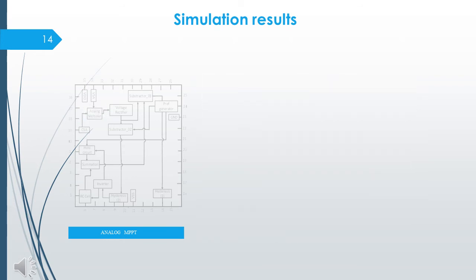The schematic circuit and its symbol of the Schmitt trigger, hysteresis, is shown in this figure. The following figure shows the transfer function of the hysteresis 1 and hysteresis 2 blocks. The bandwidth 1 of the hysteresis 1 block, well defined by epsilon 1 and epsilon 2, is set by the user and is based on current ripple and modulation frequency considerations. The bandwidth 2 of the hysteresis 2 block, well defined by epsilon 3 and epsilon 4, must be greater than bandwidth 1.